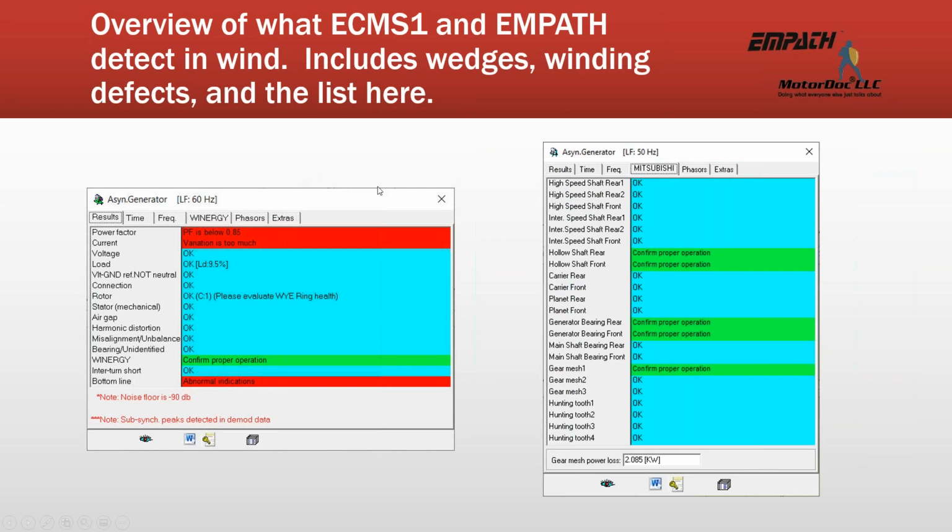So when I put in gearbox information as well, it will identify if I have a potential wiring issue. It wants to trigger you to go take a look, because a wiring issue can also look like a bad brush, or even a shorted shunt on a brush. So there are specific things we look for in that. Then this flags us over to here.